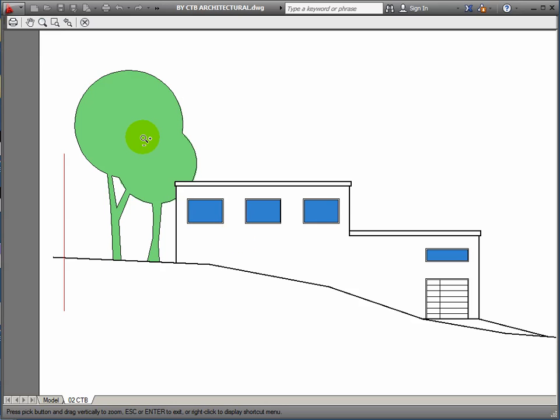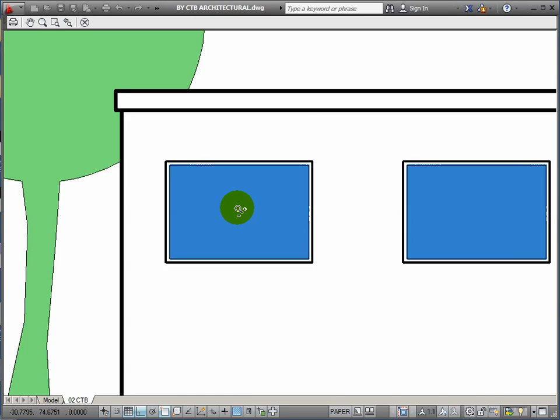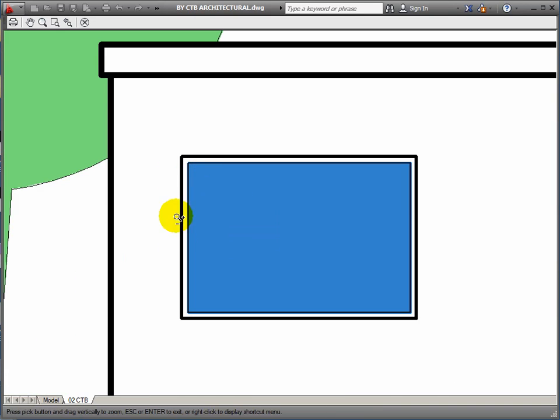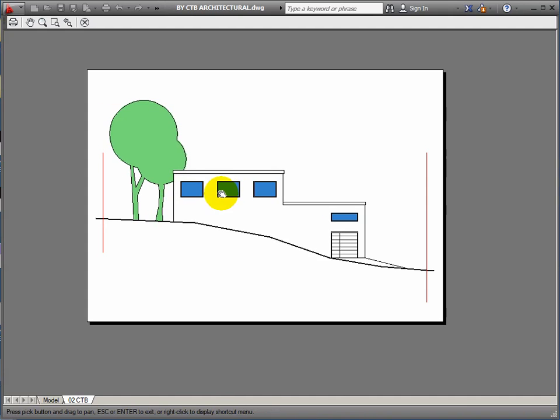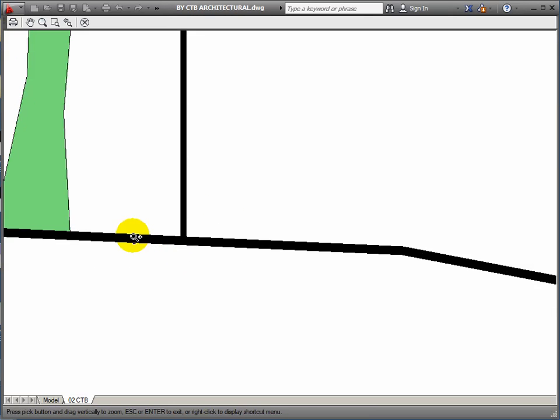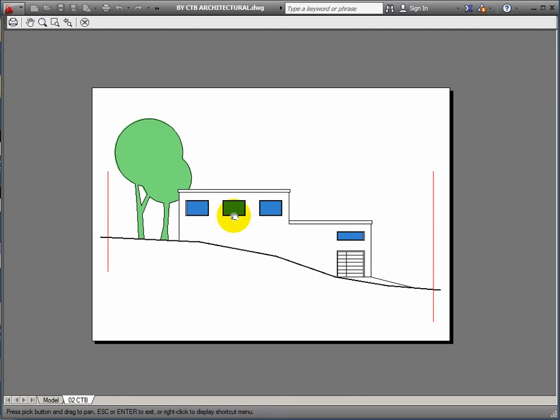I've got a thin line around the trees and a toned down hatching there. The window fill isn't overtaking the drawing. Okay, I've got openings highlighted using a fairly thick line and then a very thin line for the window frame detail. Nice strong line for the outline of the building, and I'm saving the very thick line for the cut through the ground.